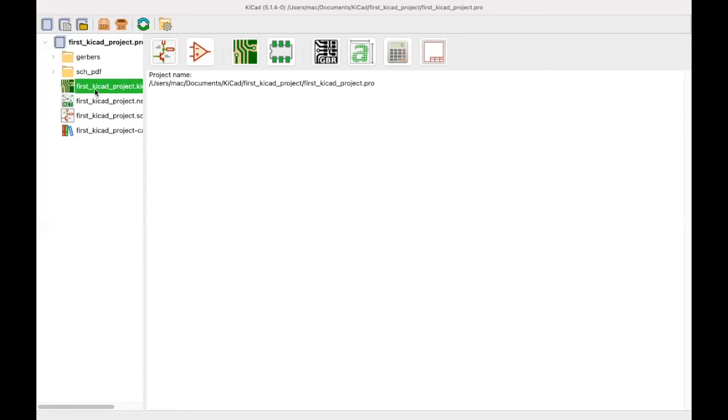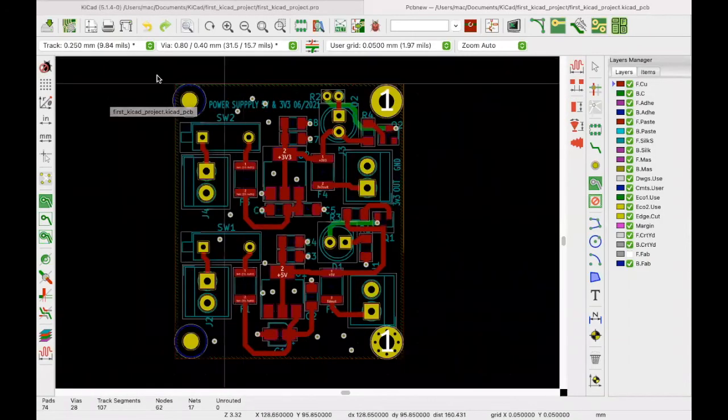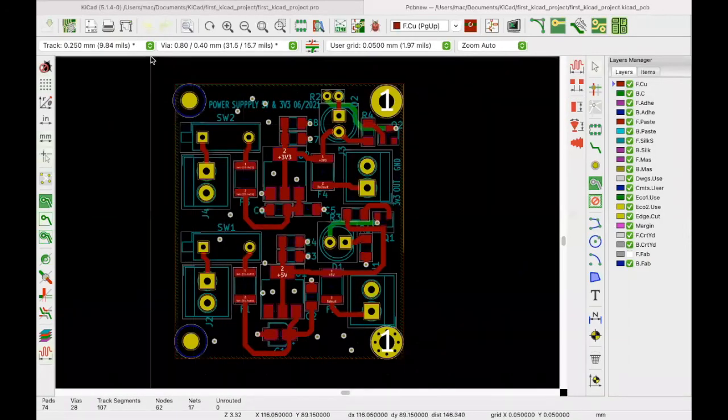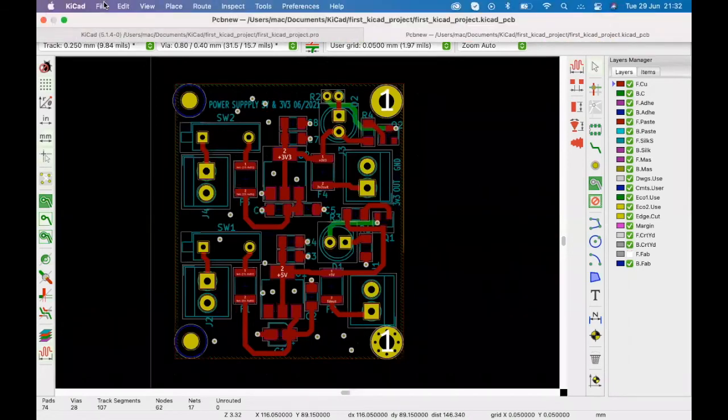So what I'm going to do on our design is fire up the board file itself. To change your board into a 4-layer board, say we've seen that our components cannot fit. We have routed the board, and we are at a point where we can't route this board again on 2 layers. Our top layer is filled up and our bottom layer is filled up.